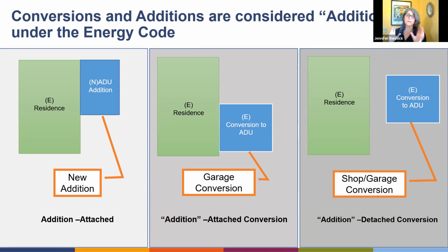So when you put one of the new heat pumps in, the mini splits, you're going to get heating and cooling automatically. If you only want heating, you actually have to have it set in the factory, where they set it up so that it locks out your cooling. So I've had a lot of clients that once they realize that, they just get heating and cooling in the same heat pump, install it, call it good, and the new occupant of the ADU gets both.